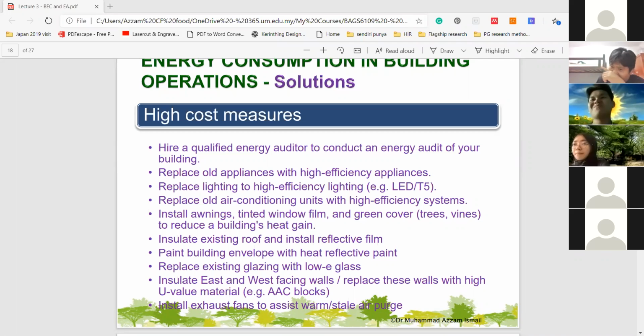When you look at glass and the U value of glass in comparison to, say, an AAC block, an autoclaved aerated concrete block, in comparison to, let's say, clay bricks or even cement bricks, or timber, the U value differs widely. Okay, and then basically it shows how much heat can be transferred through the material. So timber will probably have one of the best because it doesn't really absorb a lot of heat anyways. But having said that, something contemporary close to bricks is AAC.